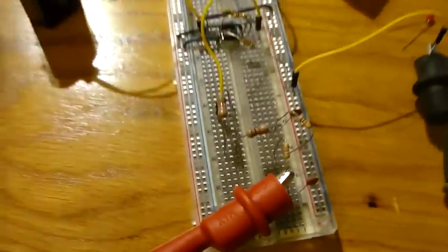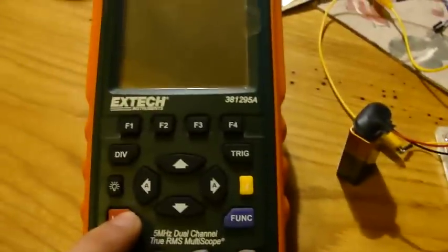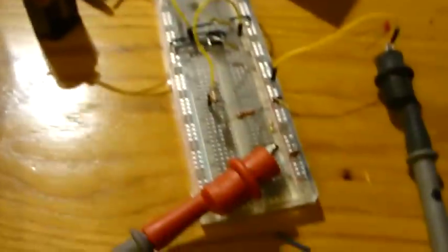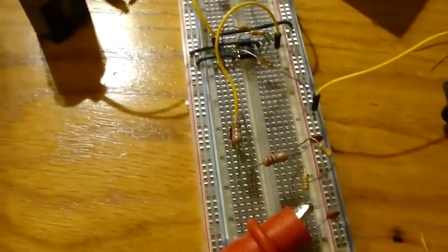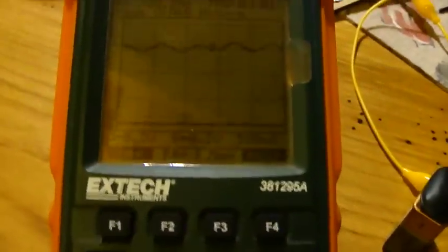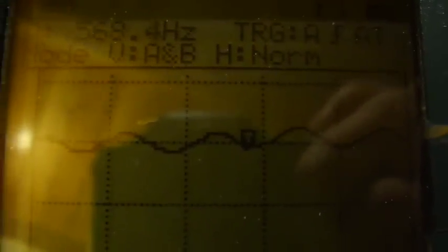So here's the relaxation oscillator with two low-pass filters hooked up to it now, and the output is being fed into the oscilloscope. One major difference, however, is the relaxation oscillator's frequency has changed. I changed out the capacitor for the aluminum foil plate, which will be the antenna, and I believe I changed out the resistor to 100K. It might not be 100K, it might be 4.88 megaohms. But as you can see, when my hand is far away from the oscillator, it's at 198 hertz. But when I move my hand very close to it, I can get up to almost 600 hertz.